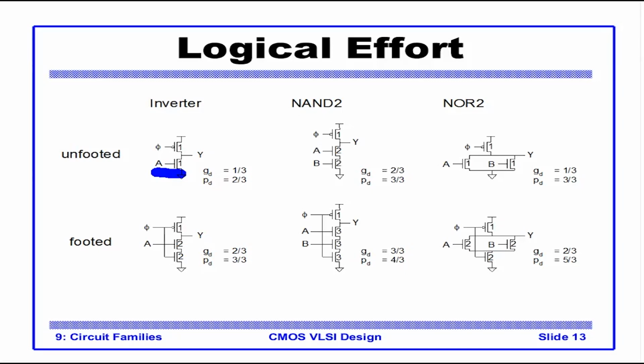Although dynamic logic adds an extra PMOS at the header and in the footer, so 2 extra transistors for the footed one, it actually reduces transistor count for a big gate because the PMOS pull up network is not there. So it takes pseudo NMOS and adds some improvement over it. It adds the clock just to prevent current leakage whenever the output node is driven by the pull down network. So now let's see.